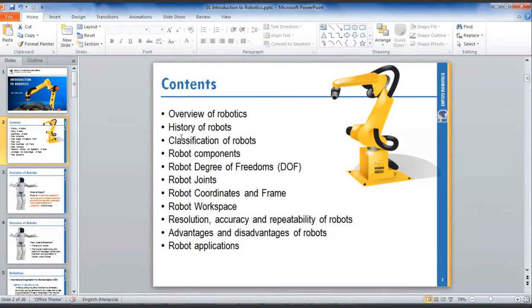But to develop the DH parameter table, you need to have a good imagination of 3D. If you make a mistake in imagining, you will get a wrong DH parameter table. Then when you develop your formula, you will get a mistake during your calculation.